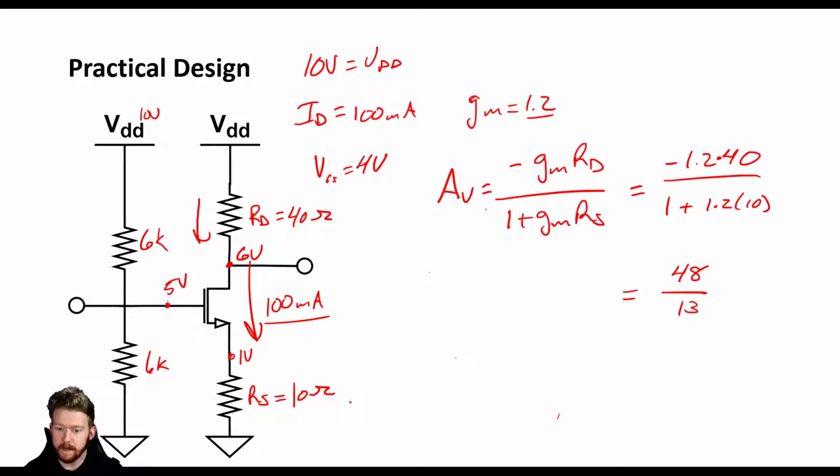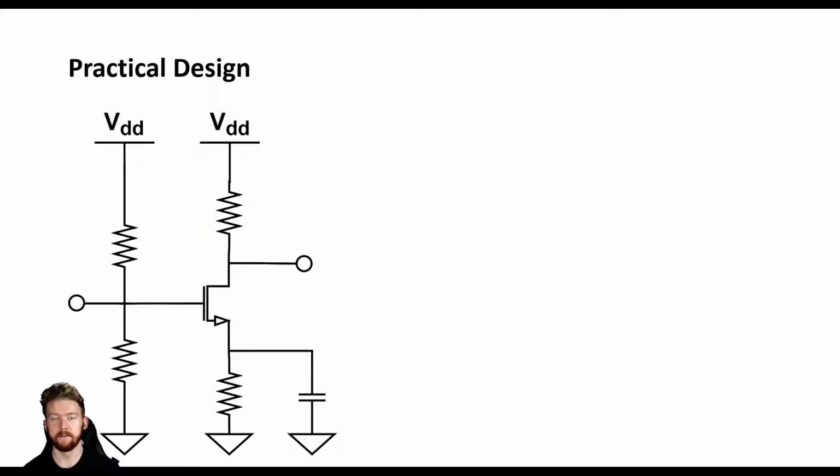So what we need is a way to have this drain resistor present whenever we are looking at only DC, and whenever we're looking at AC, we need that resistor to disappear. So we need it to maybe be a short circuit. The way we can do that is using a pretty cool engineering trick. We're going to use a component that at DC is an open circuit and in AC starts looking like a short circuit. Do you have some thoughts about what it is? Maybe some alarm bells in your head are going off. It's a capacitor. So if we add a capacitor right here,